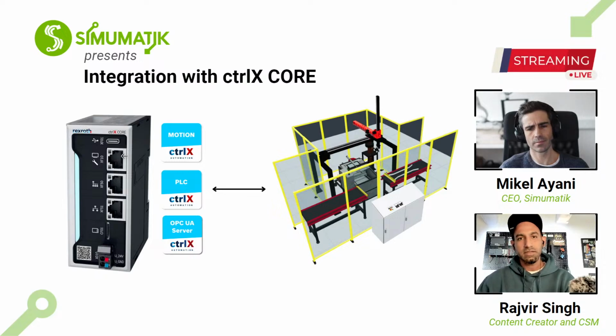I have a rack, and it has been connected with an Ethernet module and digital IOs, so you can connect further modules next to it. That is possible. And they do standard Ethernet-based fieldbuses, like Profinet or Ethernet IP. You can do all those, but specifically I use EtherCAT for reading from my IOs. I have an EtherCAT hardware module connected to it. But for sure, you have flexibility to connect to different protocols when you have these Ethernet ports available.